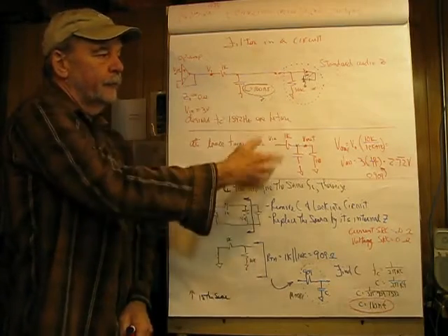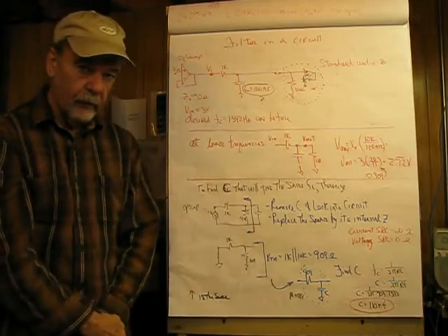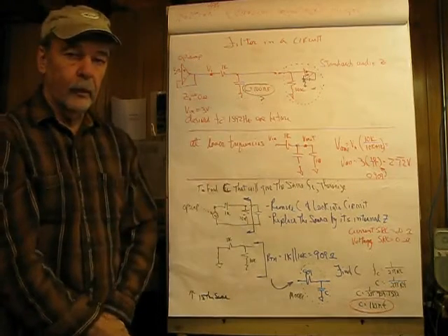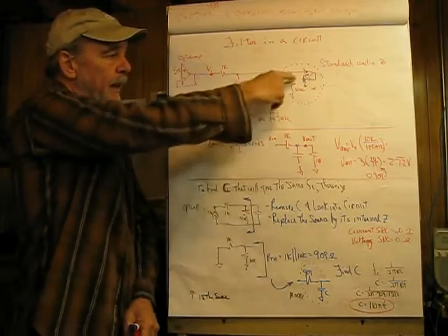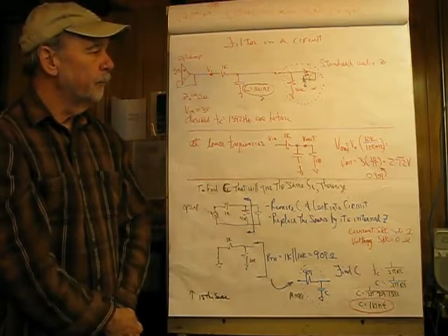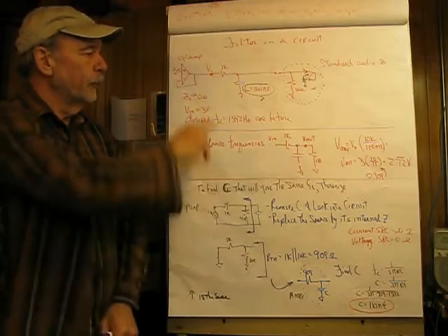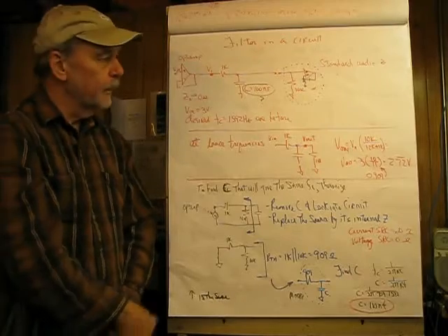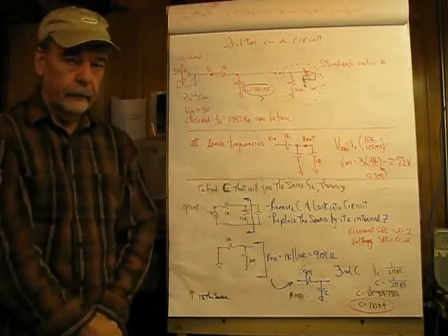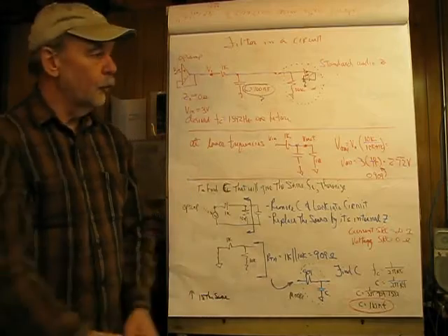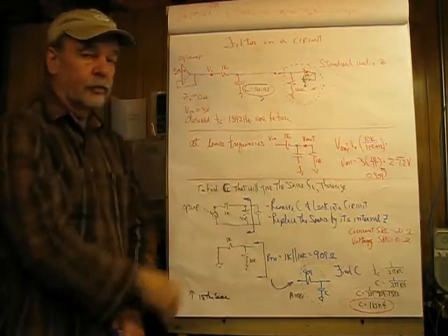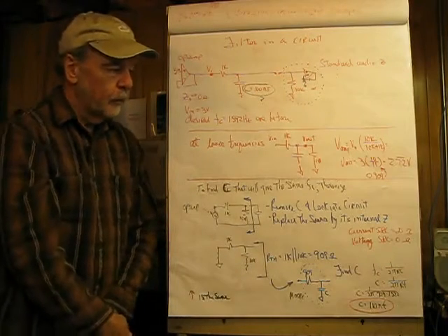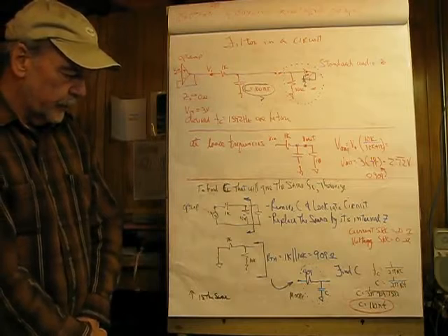And if we weren't dealing with the audio impedance level of 10K, we could make this say 100K and just simply not worry about it. But we do have to have a path back to ground in this case. And also note that any DC offset here is going to drastically upset this op amp. So there's no DC blocking. And we could fix that if we wanted to by putting a really large value of C in here, which wouldn't affect the frequency, but it would block DC. So there are some nuances in here we have to be a little bit careful of.